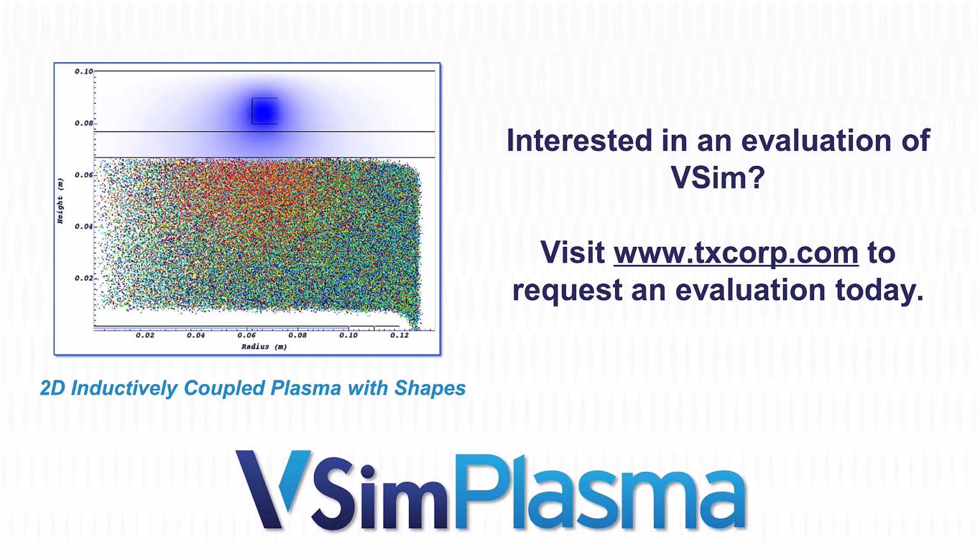What are the pressure limits for these simulations, and what was the pressure in the simulation shown? Pressure limits, it doesn't really have any limitations. The simulation that we showed has a 100 millitorr pressure, so it's pre-collisional. The use case for using a kinetic code would be to run at lower pressure. At higher pressure, you have to resolve the collision frequency, which can become computationally expensive.